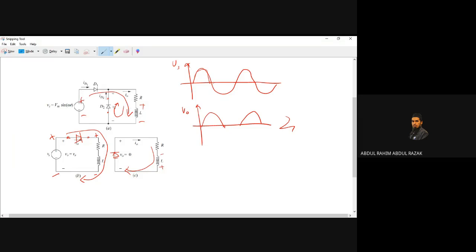Just now the current flowed from here, it could not enter the diode because it's reverse biased, so it went into the load, back to the source. When you take out your source, there's remaining current inside your inductor, it has to flow. And because the diode is a short circuit when forward biased, it flows here back to R until it goes down to 0.